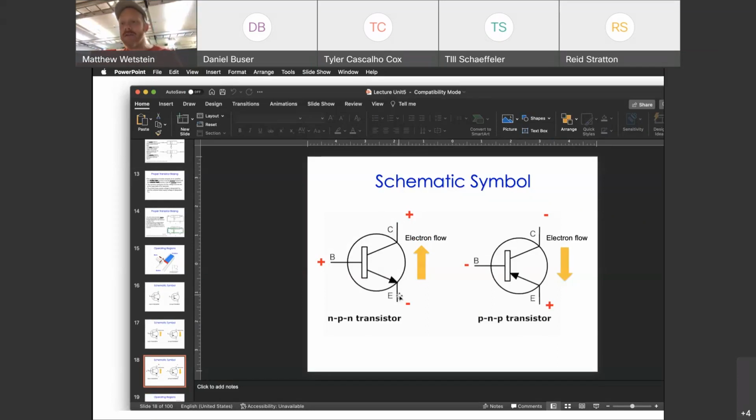Now, what I think confused a lot of you is that in previous problems, including ones that I did that day, we went the other way. We said the voltage at the emitter is blank. What is the voltage at the base? And for that, you add 0.7.